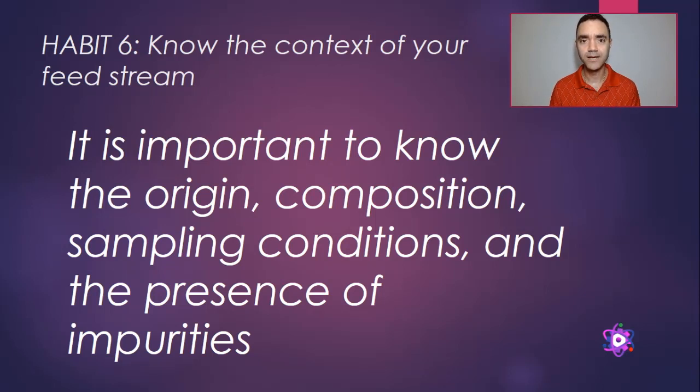For instance, when I'm dealing with purification of hydrocarbons, or dehydration of hydrocarbon, I get the chromatography results, and the chromatography results is an analysis based on dry conditions. And depending on the conditions of my feed gas, it can be saturated. So I need to understand that before adding the components for my process simulation.